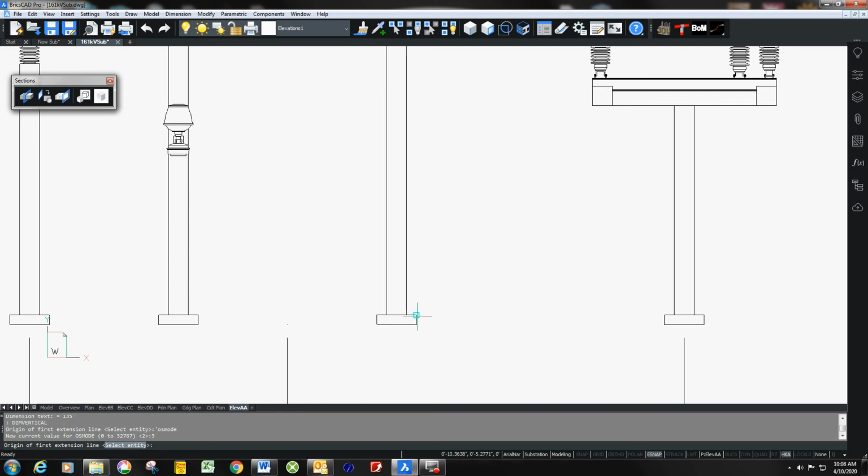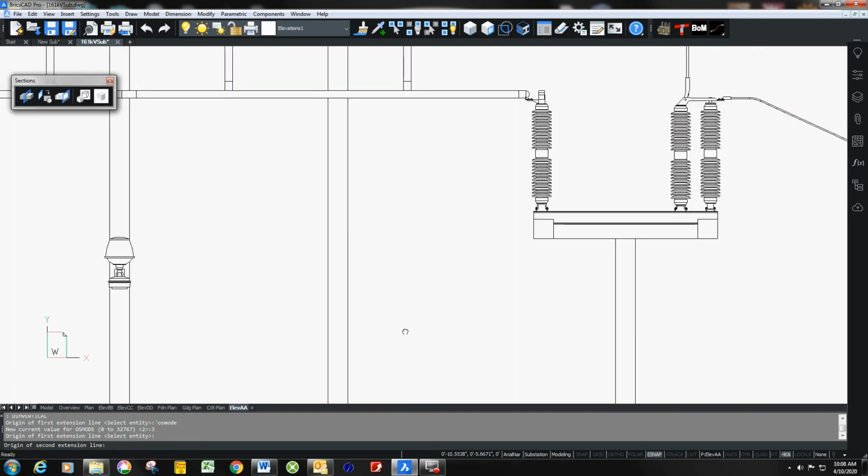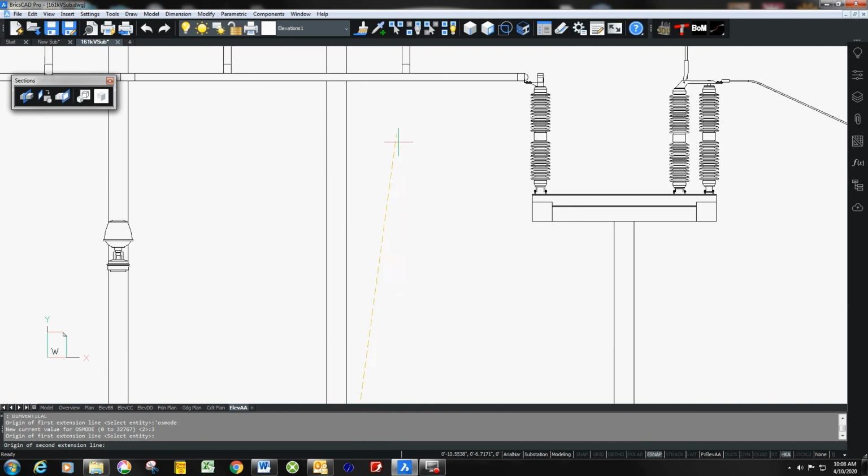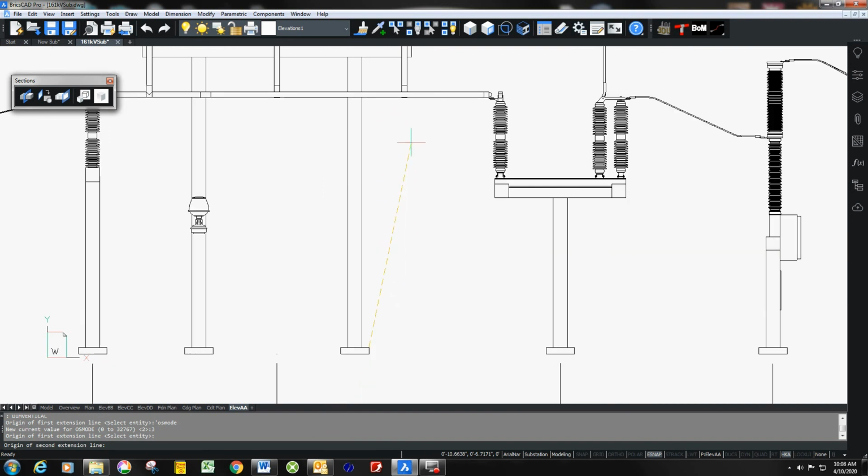Because I want a dimension from the top of this footer. The top of this footer ought to be somewhere above ground, maybe by 1 inch or 2 inches. But if we give them the dimension of that footer, then we know that it'll be above ground, somewhere up here on the structure. And so here we have one.